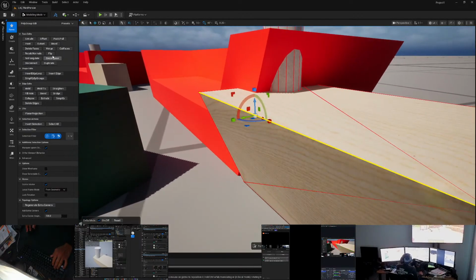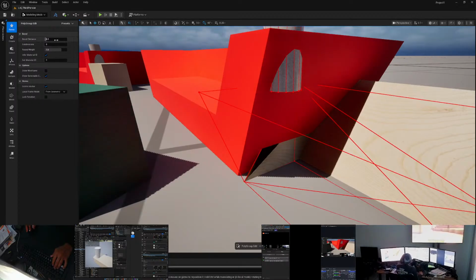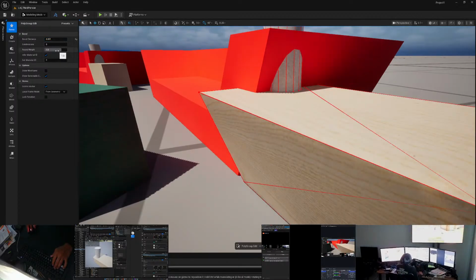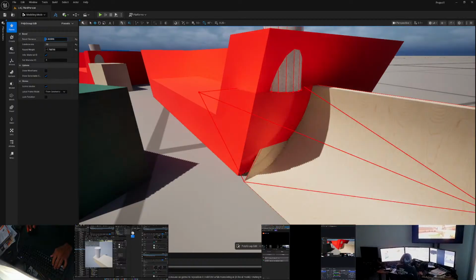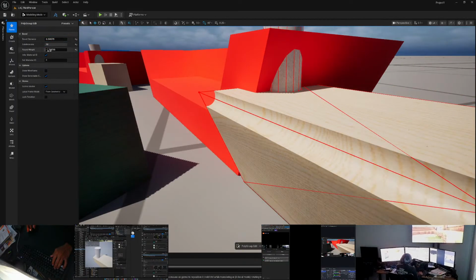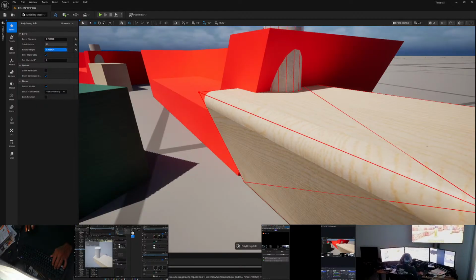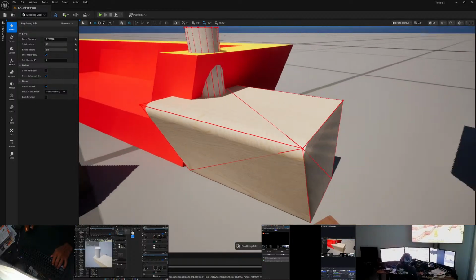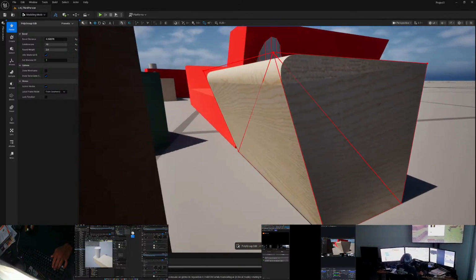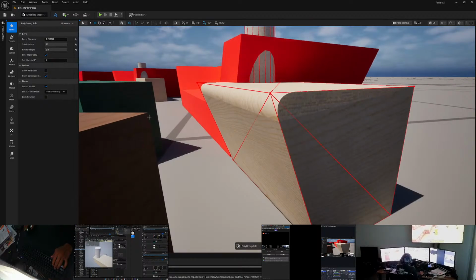And then I'm going to bevel that edge. I'm going to set this back to 0. Set the round weight to something really small. Subdivide it. And let's see. Set the round weight back to something positive. And now we have a custom table.